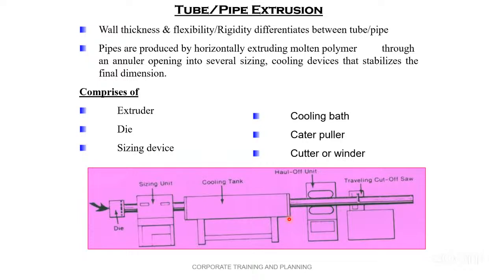Correct, correct. Why this? Means some material we need to cool faster. Like if nylon material is there, we should not cool it too much, because while doing the cutting at the pelletizer, it will not cut. Some soft material like PP and all, we can cool it and we can cut in the pelletizer. For that reason. Correct, correct.